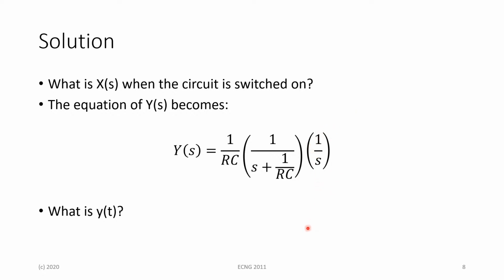If our step response had a different magnitude, say that it went from 0 to like 12 or 0 to 14 and so forth, the Laplace transform is basically just going to be 12 on S or 14 on S. So the magnitude maps on the numerator here, and the denominator here will always be S for our transform accordingly for our step response.